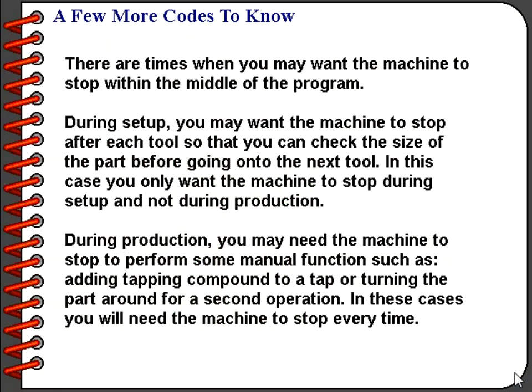There are times when we need the machine to stop for certain things. During setup, you may want to stop the machine between each tool so that you can check the size of the part before allowing the machine to go on to the next tool. Doing it this way, the setup person can almost always get the first part correctly on size.